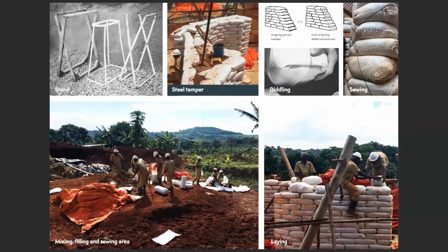The mixing, we are utilizing, of course, the soil that is from the site. We've had a lot of bulk excavations where we have extracted this soil, and of course the trenches. We are mixing this soil with some fraction of sand. Why we are doing this is because, from what I've explained earlier about the consistency of our soil, it's very hard to compact.